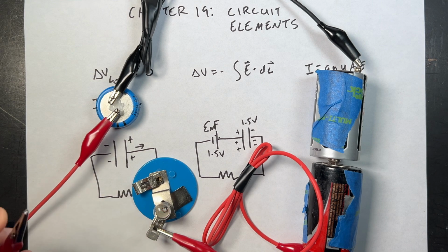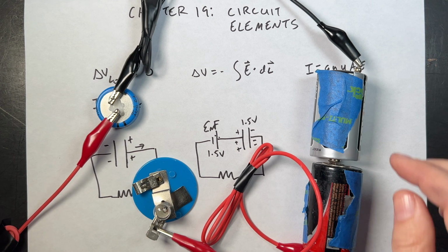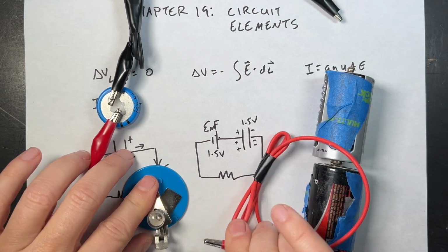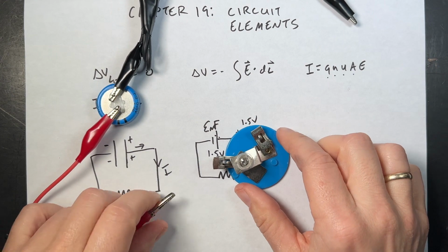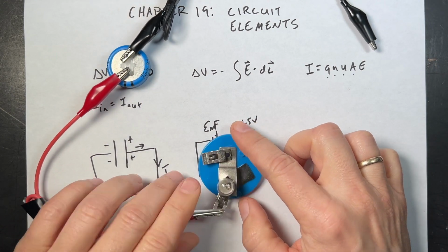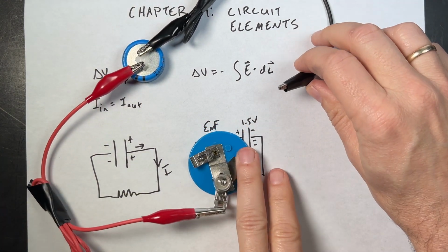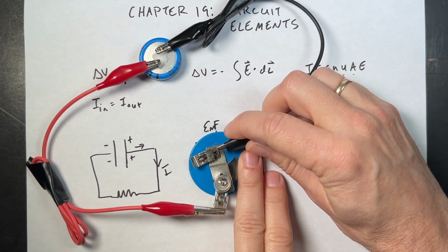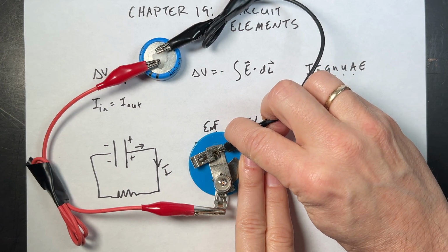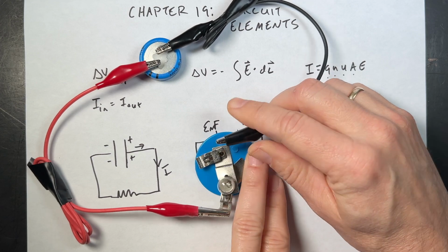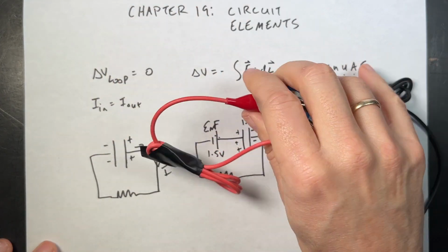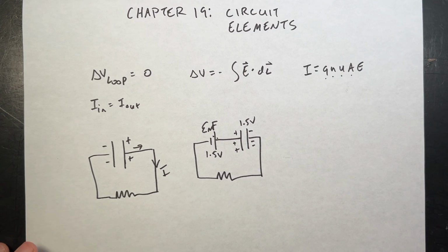Okay, that's good. Now let's do the case right here. What if I take the battery away? Now my capacitor has charge on it, and I can connect the capacitor to the light bulb. And let's see what happens. So now it starts off bright, not super bright because it didn't have a charge all the way, and it dims down. Okay, so that's what we have. And I'm going to solve this problem for you in a short bit.